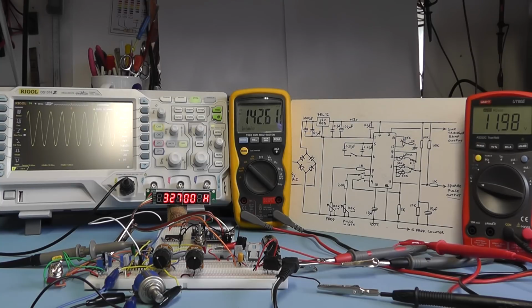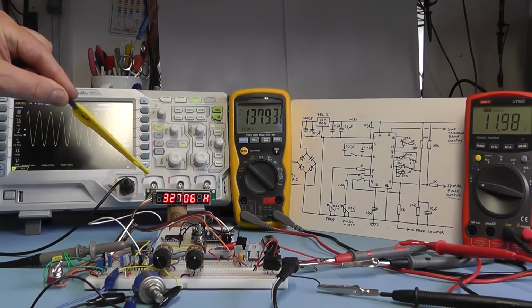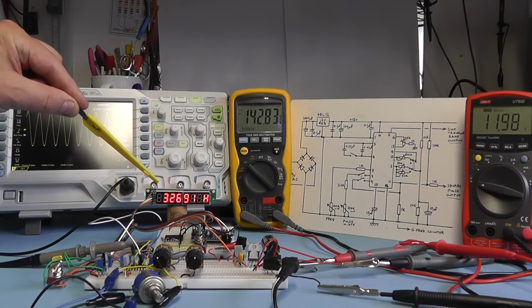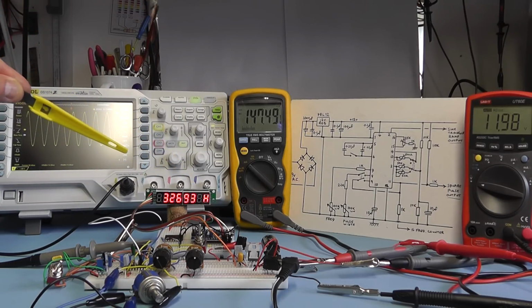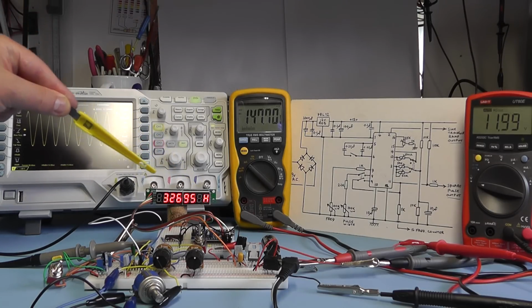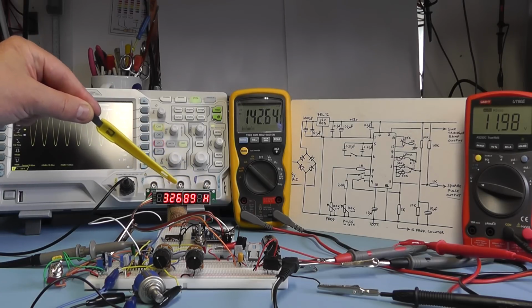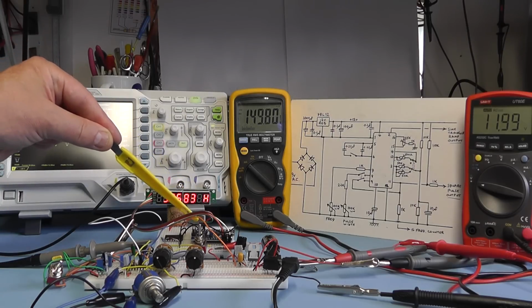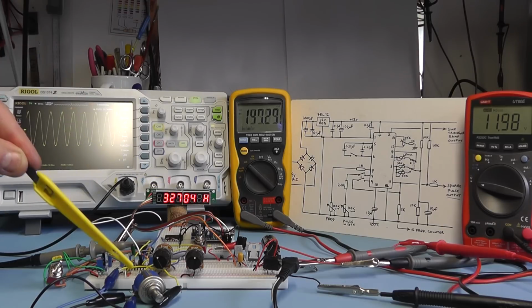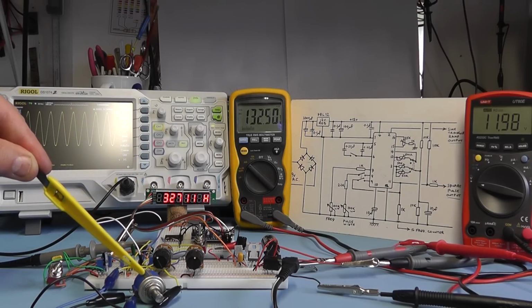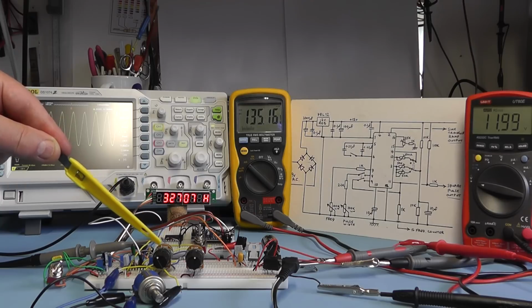Let me see. Right, we're probably now at the top end of the range of the frequency counter here. It's showing 32,697 or thereabouts Hertz. Certainly when I go anything over 32,768 it stops functioning, the counter. So that must be a function of the way we're using the Arduino Nano. It's probably something to do with the timer we're using in the Arduino Nano itself, not capable of going higher than that. But I think the multi-turn pot here, 5K in series with the 100K pot, is a good addition to give you more control over the frequency.